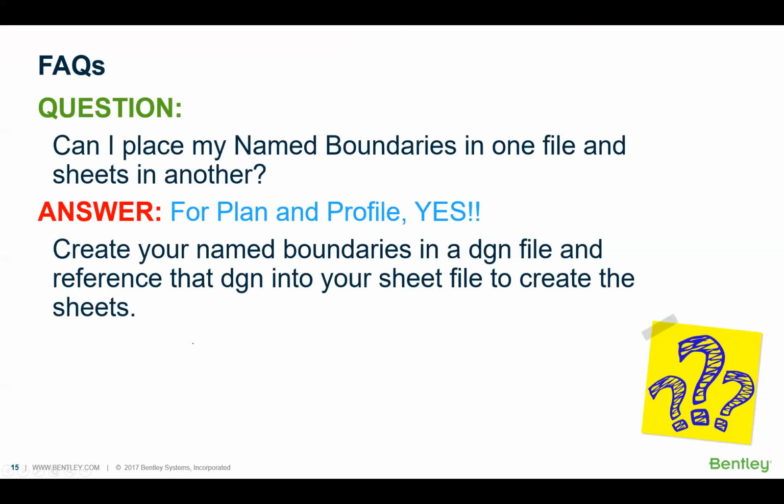So a frequently asked question we have about sheets is, can I place my name boundaries in one file and sheets in another? For that, you can. Let's say you wanted to use the same name boundaries you use for your plan sheets for something like traffic control or utility adjustment sheets. You can create your boundaries in one file, then go into another file, reference those boundaries in, and cut your sheets from the reference.